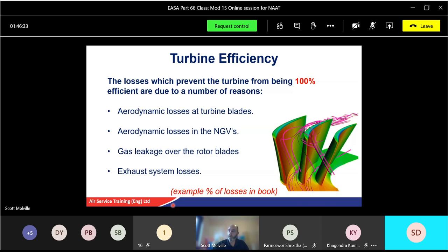So I might actually put these up in here. So 3.5%, 4.5% there, and other aerodynamic losses over there, and you'll get an overall loss, and efficiency would actually result in it being 92%. Okay, that would be on page 80 of your new book. So it's not bad, 92% efficiency, better than 50% obviously, but unfortunately we never get 100% efficiency.